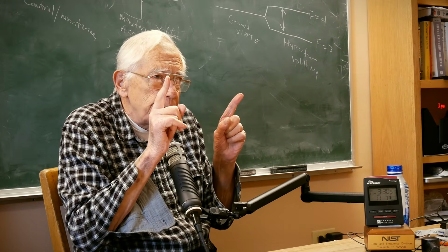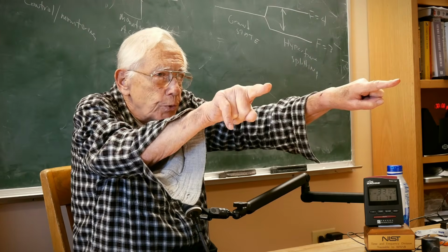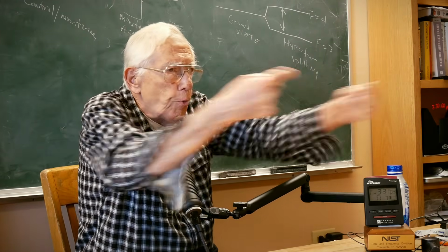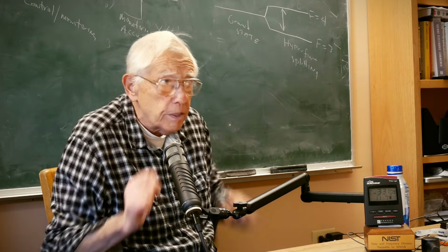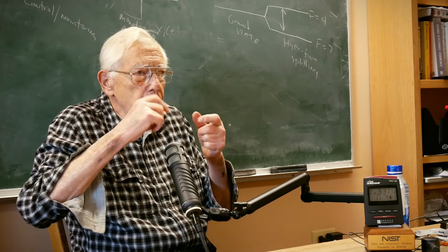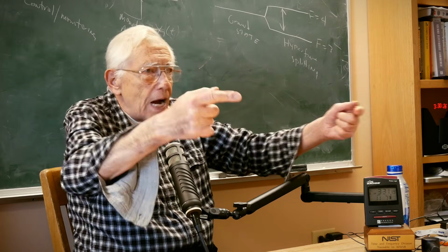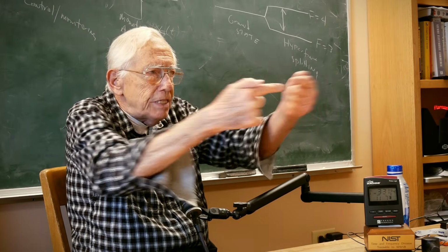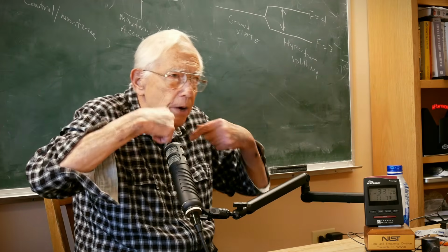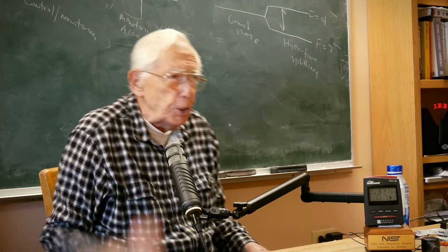The common view is really peer-to-peer, because in common view, I send a signal to you too, and I don't participate in the difference. You participate in the comparison. So common view is really closer to peer-to-peer. The two-way is really closer to leader-follower. I send you the time and you follow it. Whereas in common view, you compare clocks together, and the accuracy of the comparison does not depend so much on my accuracy because it cancels in the difference. So that's method number 2.